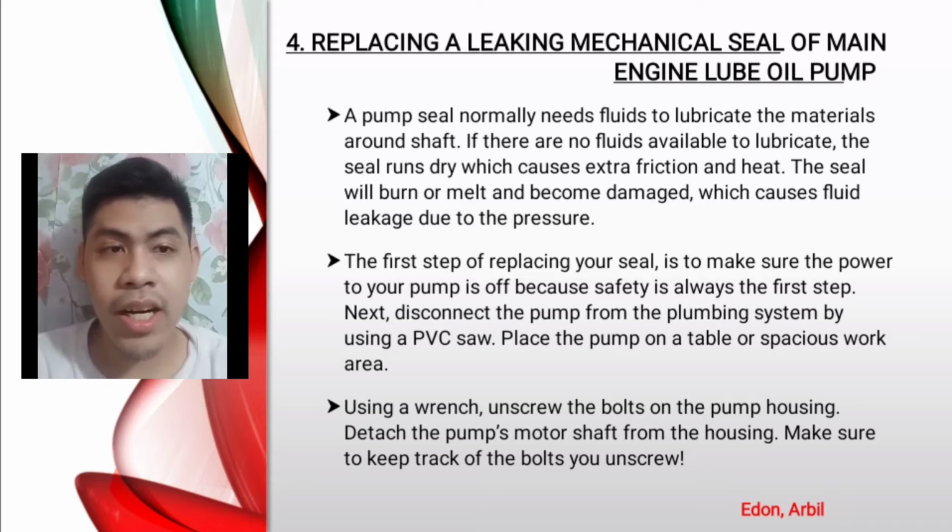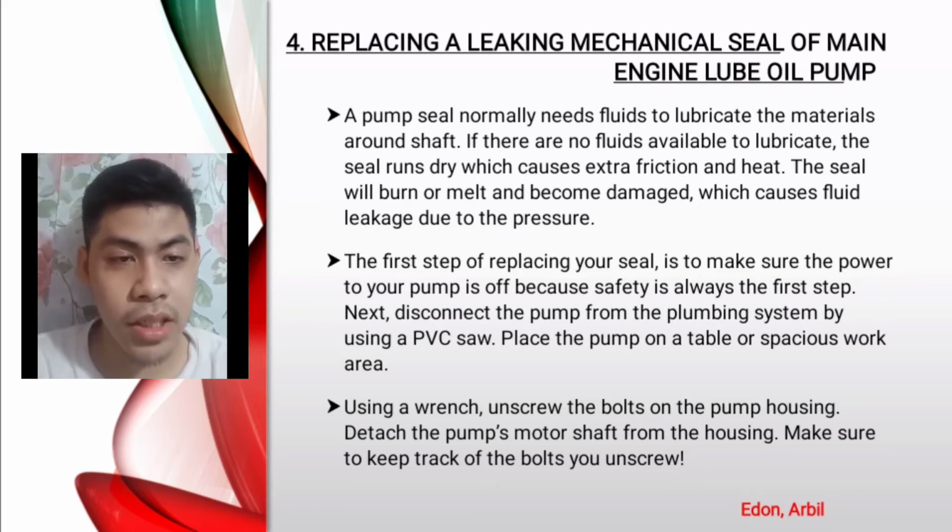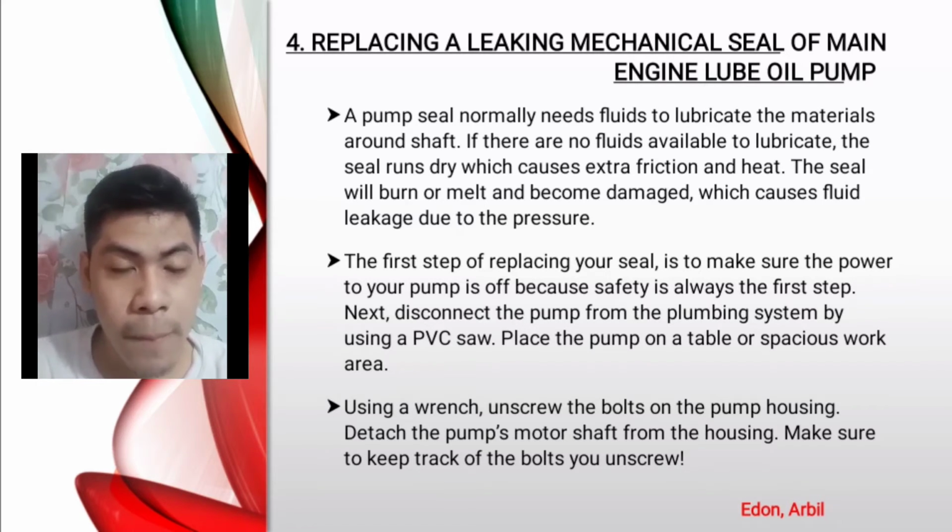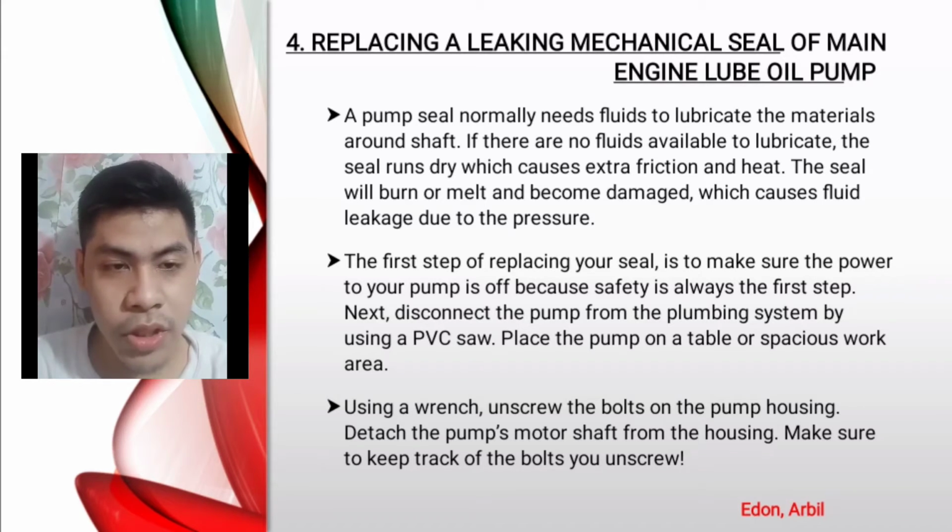So there are steps for replacing your seal. First, make sure the power to your pump is off, because safety is always the first step. Next, disconnect the pump from the plumbing system by using a PVC saw, and place the pump on a table or a spacious work area.